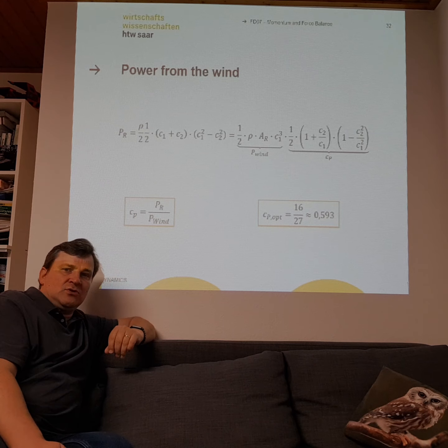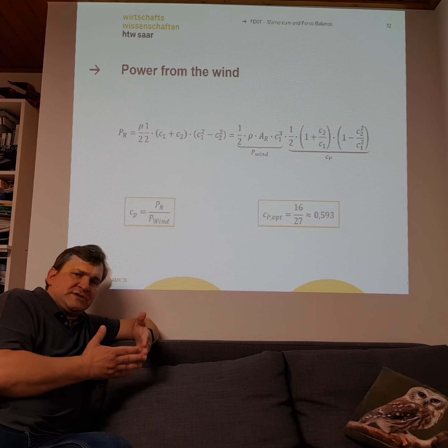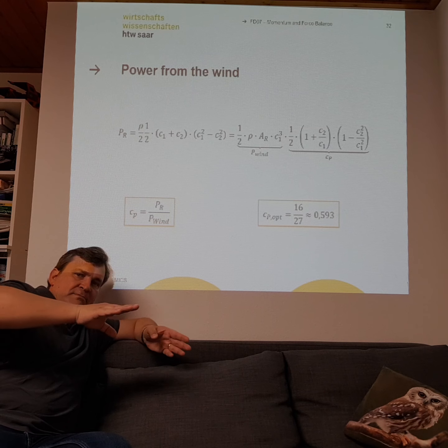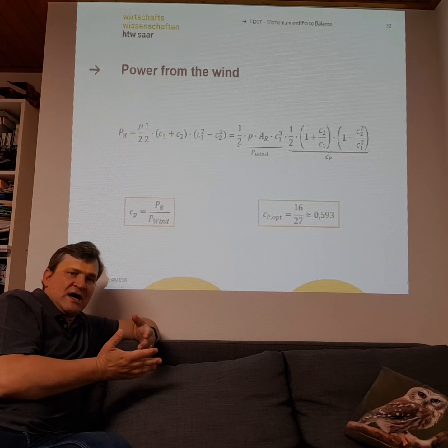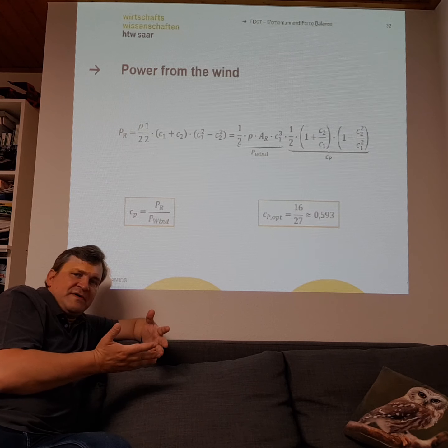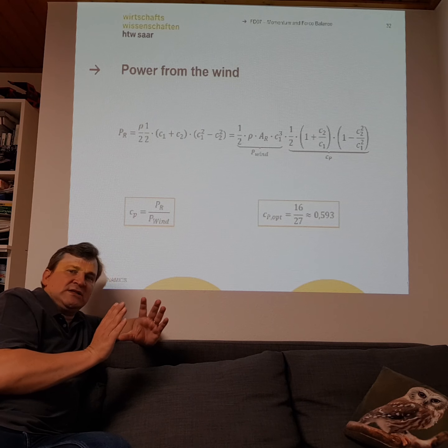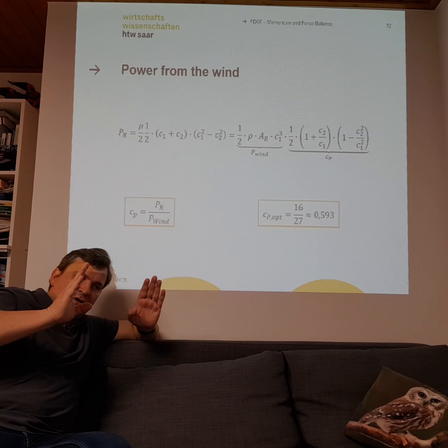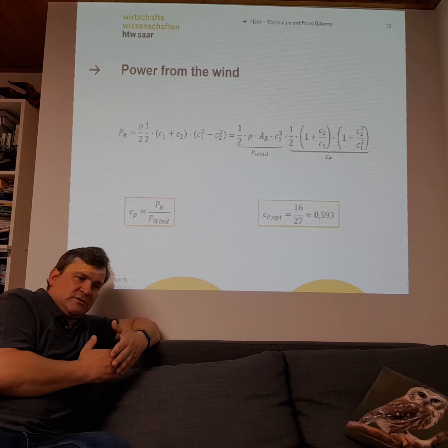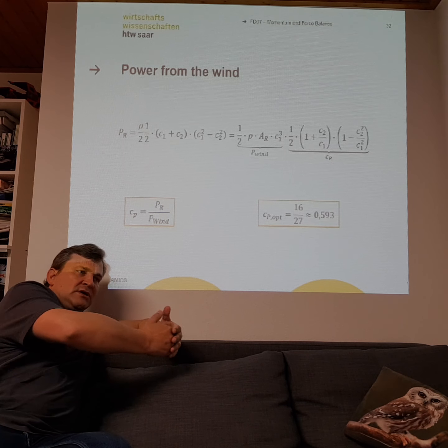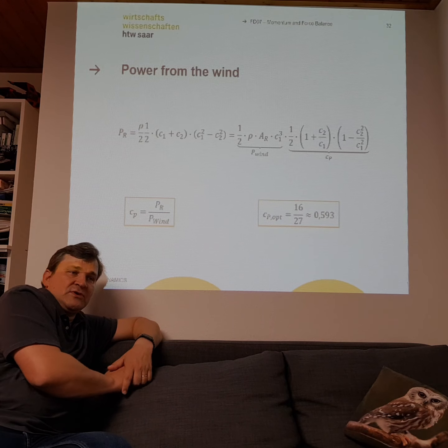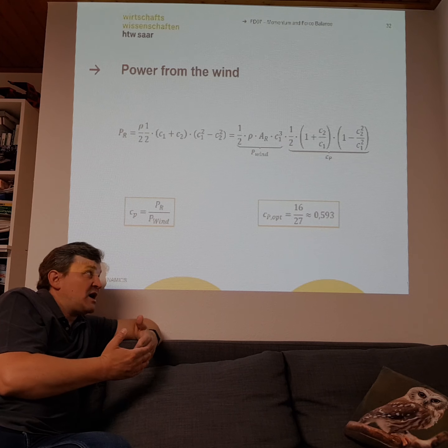But as you learn from the sketch of the CFD calculations, and also from the theory, you get a bigger area of your fluid after the windmill and a lower velocity, and because the fluid is not channeled in a duct, the fluid can go around the windmill. You can't get a real pressure difference between the area in front of the windmill and the area at the back of the windmill. So you can't get an efficiency of 100%.